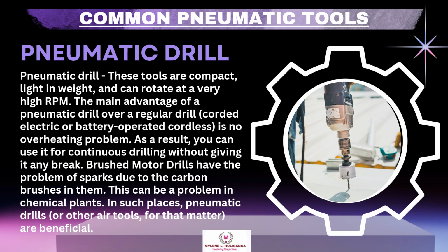Brushed motor drills have the problem of sparks due to the carbon brushes in them. This can be a problem in chemical plants. In such places, pneumatic drills, or other air tools, for that matter, are beneficial.